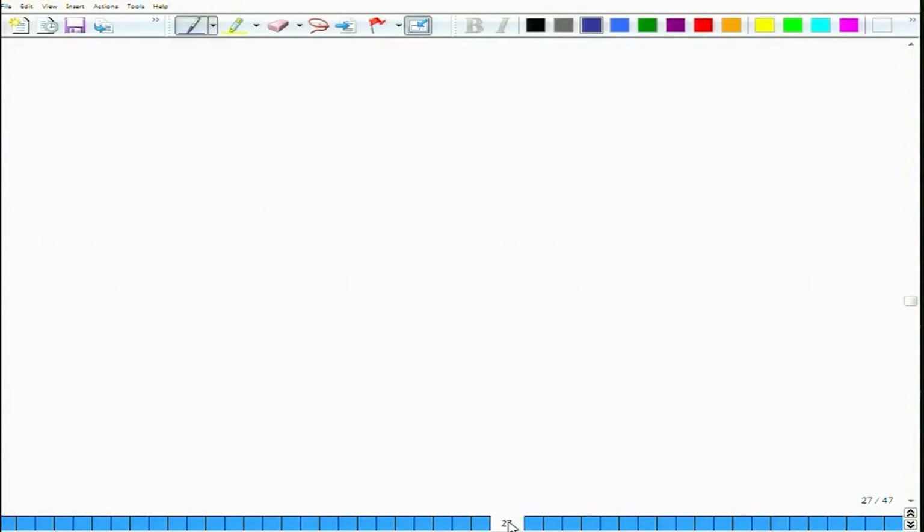So what we do is we construct a laminate and we will say that it has just 4 layers, 0, 45, minus 45 and 90. Okay. So it may not be symmetric, but if I just reflect it on the other side, I can make a symmetric laminate. So that is not the point. Okay. So this is a quasi-isotropic laminate.